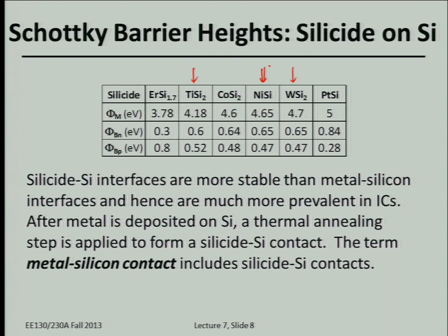But these chips might be millimeters or centimeters across. And if you remember from one of the previous lectures, resistance is equal to the resistivity times the length divided by the cross-sectional area. Typically, the thin films of interconnects are less than a micron thick. It costs too much to deposit something much thicker than that. And the width of these interconnects is also typically less than 1 micron. So the cross-sectional area is like 10 to the minus 8 square centimeters. The length can easily run to millimeters.